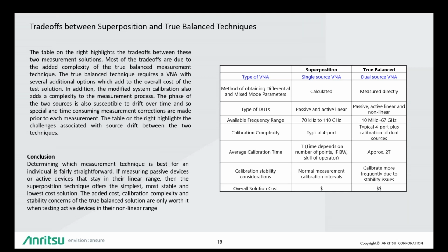It is because the input VSWR, or the return loss of the device, is constantly changing. Therefore, to keep track of that, you need sources that are phase coherent. That's why it is best to use the true balance technique for those types of applications.